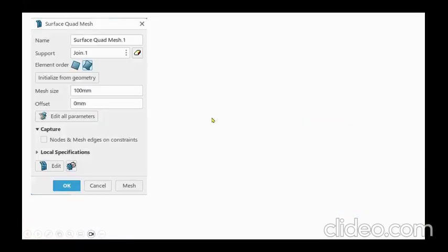Now, when it comes to meshing, in tutorial 11, I said that you have to make sure that the duplicate nodes are merged, because the duplicate nodes are nodes that are in vicinity of each other. In my case, in that problem it was 10 millimeter merged, but we don't have to do that, because once we download the step file, then we create a single surface and we can mesh the whole thing. Okay, that's why I'm not worried about this particular pull down menu.